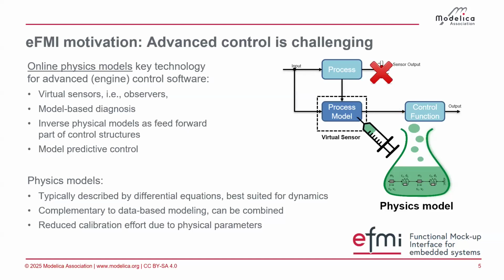So we have a lot of these things. We have virtual sensors, model-based diagnosis, like fault diagnosis. In the car, is my suspension still working? Is something broken? What is with the wheel? We can reuse our equation-based models to do inverse plant model design. So we reuse the physics and we ask the question the other way around, not how does the system simulate, how does it behave? We ask the question, what are the stimuli I have to give so that the system behaves like this?